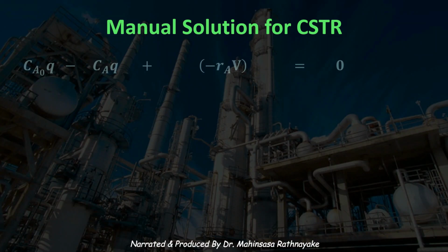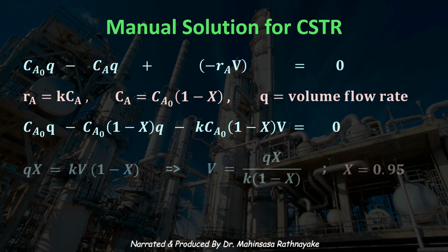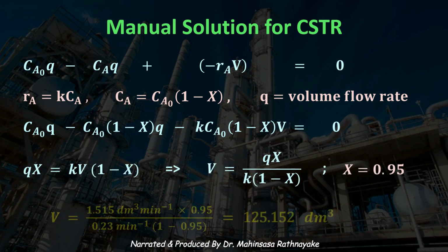Next, we will compare these simulation results with manual calculations. For CSTR, analytical solution using manual calculations gives us at 0.95 conversion the volume of CSTR is 125 liters.